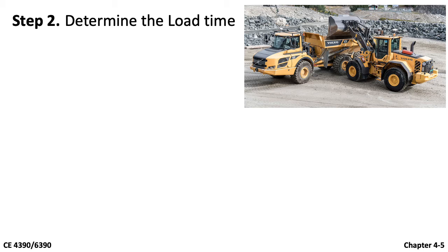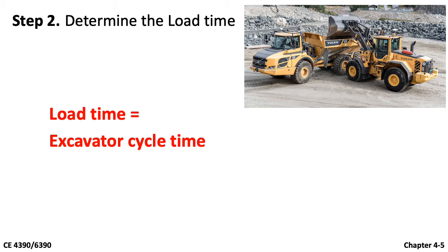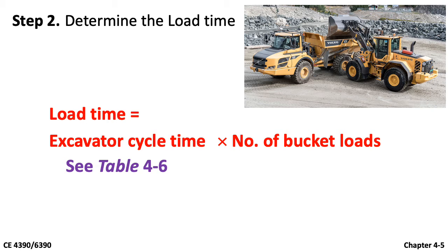Step number two, determine the loading time, or the time it takes the loader to fill the truck. It is equal to the excavator cycle time multiplied by the number of bucket loads. Since the excavator cycle time is not given yet, you need to calculate it using table 4.6.